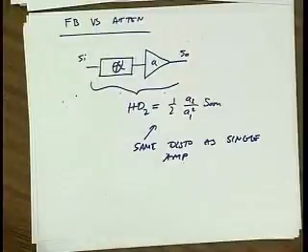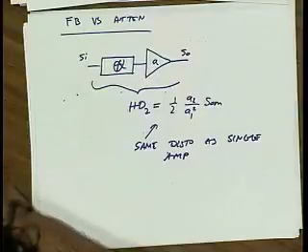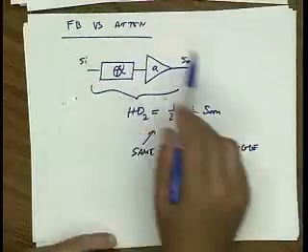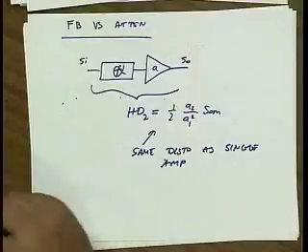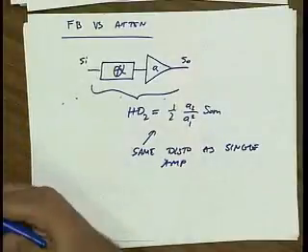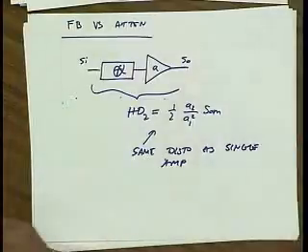Questions or comments? I mean, even if this were to give you the same advantages as the feedback system, in reality, these systems are not perfect, and they have all these problems. I mean, that's a very good point. So, just to repeat your point, even if this did have advantages, you still wouldn't want to use it over feedback, because the whole reason why we use feedback is not just because it improves distortion, but also because it makes our gain insensitive to process and temperature. So feedback has other benefits as well.